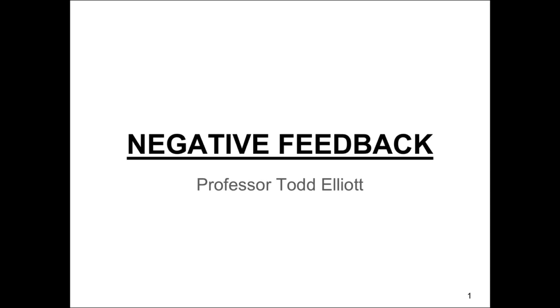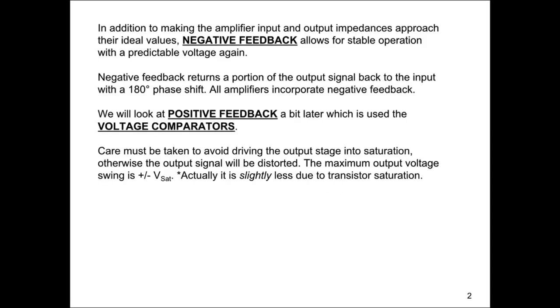To talk about op-amp negative feedback. Almost like we never left. So in addition to making the amplifier input and output impedances approach their ideal values, remember, ideally the output impedance is equal to 0 and the input impedance is equal to infinity.